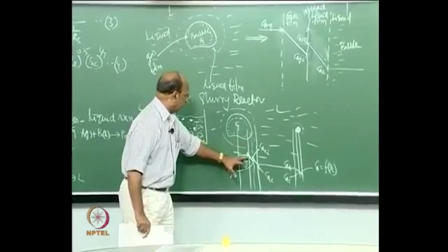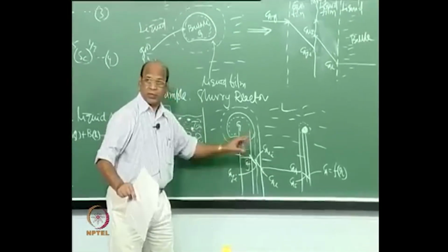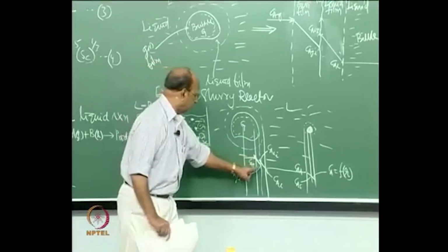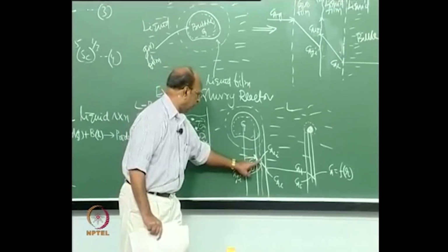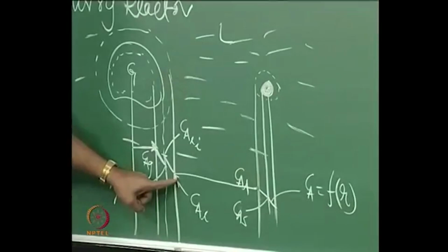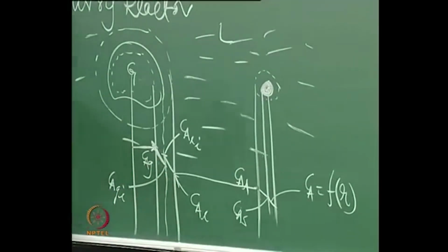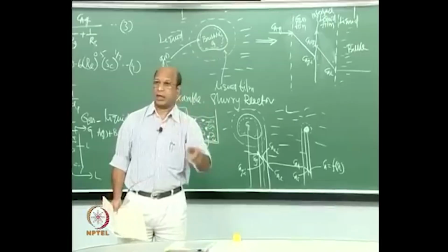So, the first step is mass transfer through the gas film within the bubble reaching the interface, from the interface to the liquid film, that is the liquid side, but surrounding the bubble. Then inside the liquid I have the same concentration because of vigorous mixing. If the vigorous mixing created by bubbles is not sufficient, then we will also put a stirrer.